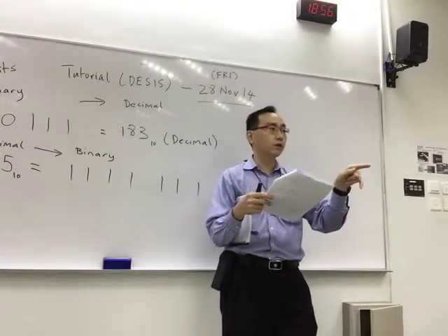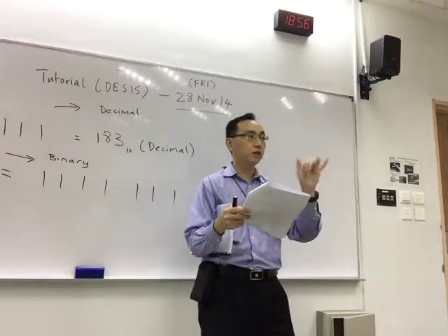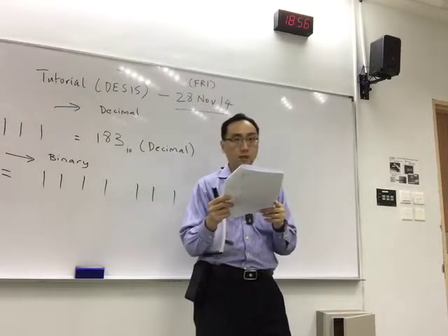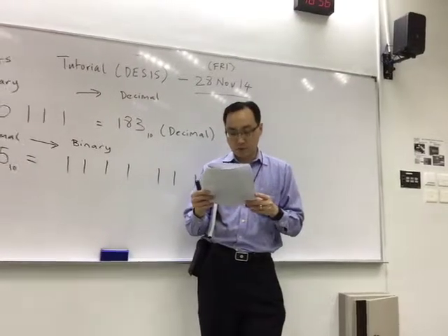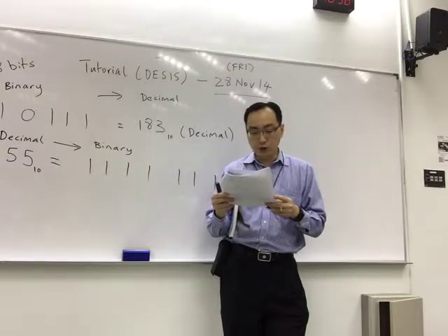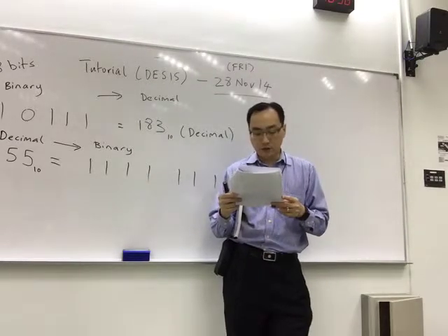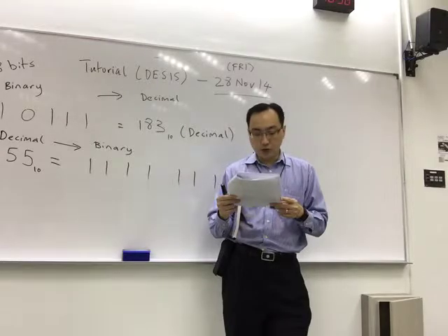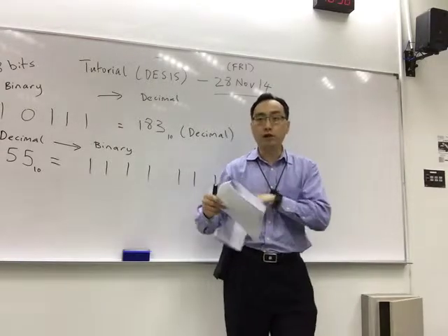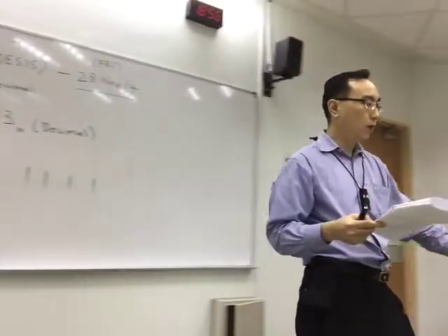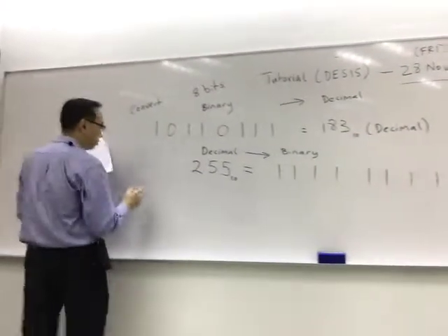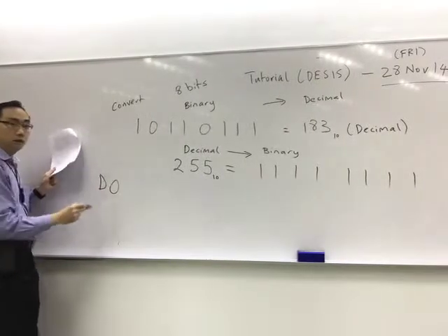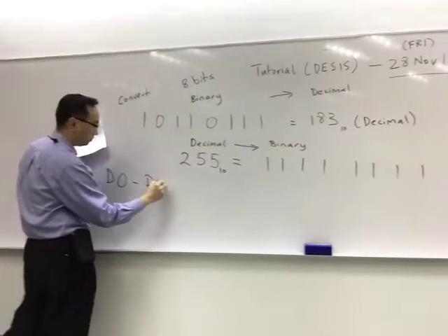Question 6. If you have not looked at the question, I'm jumping straight into the solution. Basically the answer says that you need 3 pH sensors. Any of the 3, yes. For moisture, you need 4 sensors. Then you also need the digital output, DO. Why do we need digital output? You want to control the motor, because you need to use the motor for some control. So DO stands for digital output.